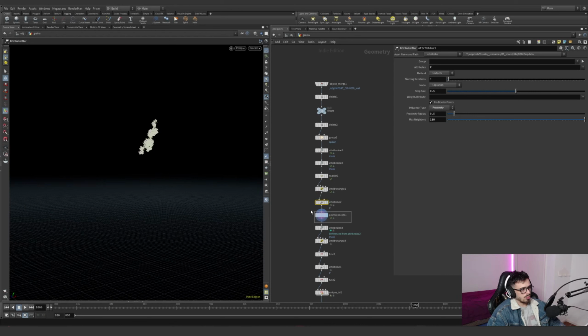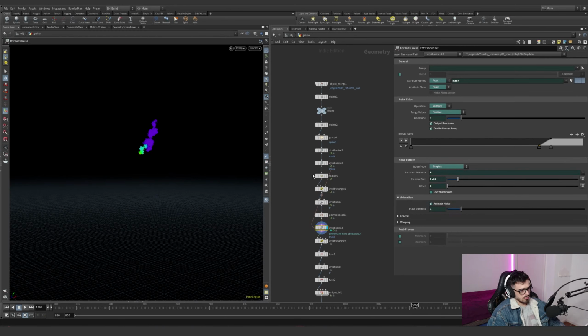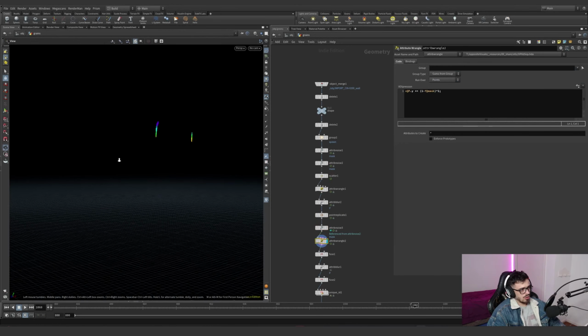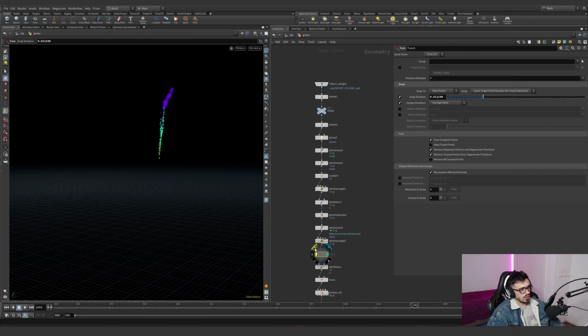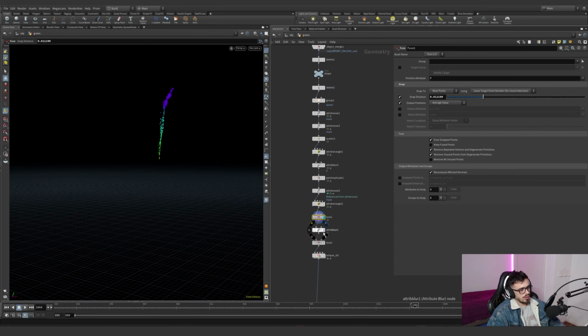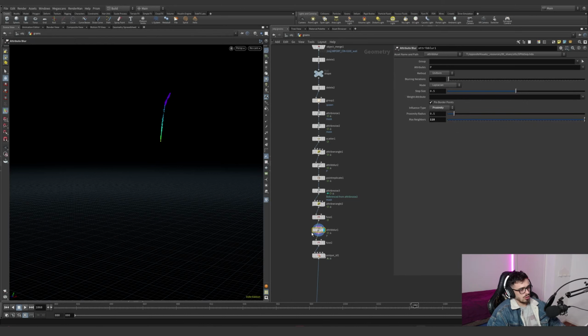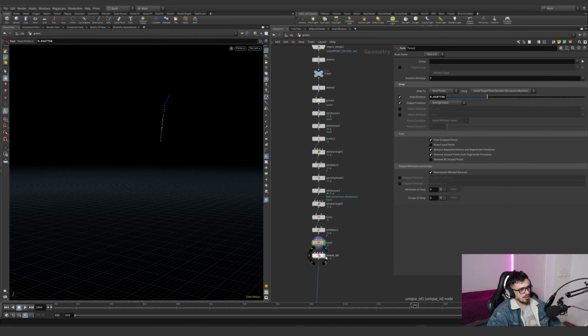I'm going to point replicate a lot, and with a noise, which is the same as this one, I'm going to reapply the noise, and I'm going to move this upwards based on the mask, the complement of the mask. I'm going to fuse all that I need so they don't overlap. I'm going to blur it a little bit more, so I'm having a line. I'm going to fuse them a little bit, and I'm going to use the trick with the unique IDs.